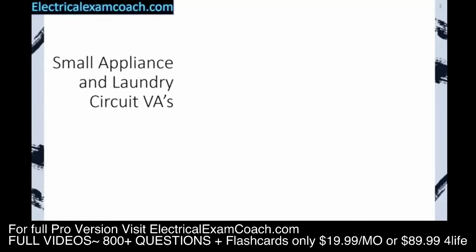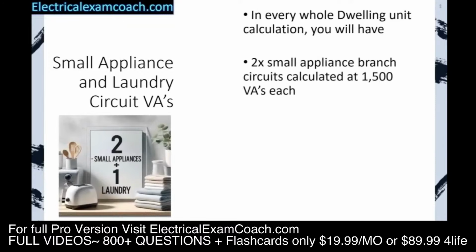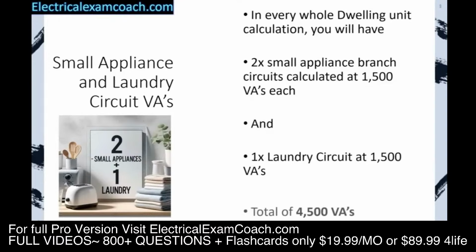Now that we've learned about our 3 VAs per square foot, now we have to learn about what's called our small appliance and laundry circuit VAs. In every whole dwelling unit calculation, we're going to have 2 small appliance branch circuits calculated at 1,500 VAs each, and 1 laundry circuit calculated at 1,500 VAs, for a total of 4,500 VAs.